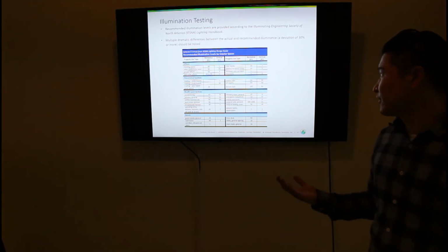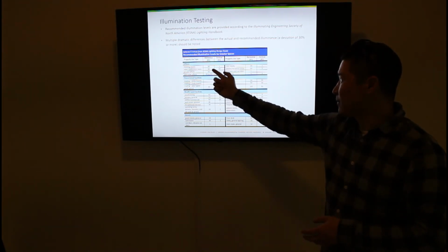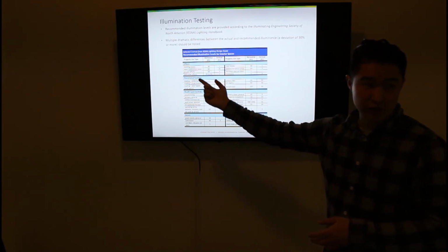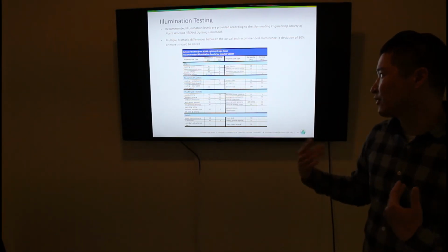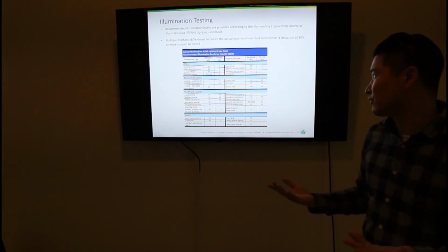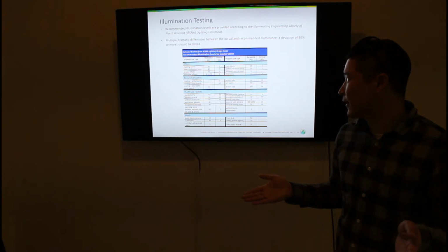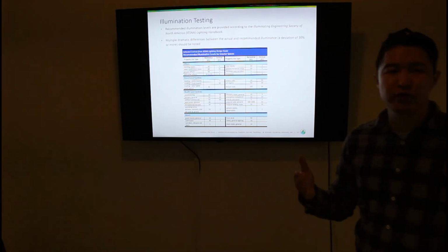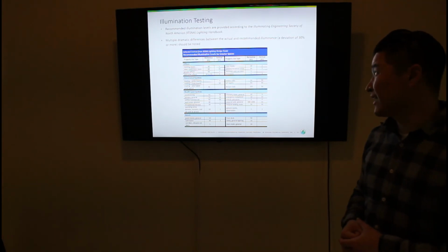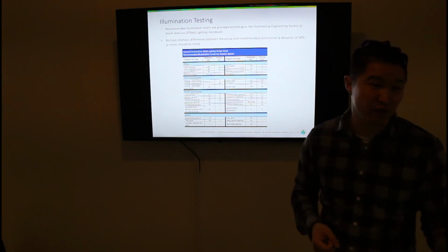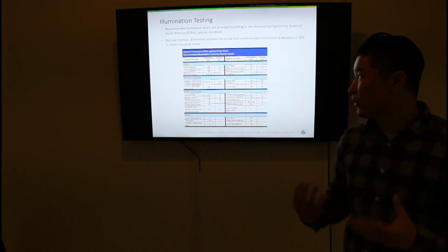For example, if you are looking at a meeting room, its recommended reading is 30 foot candles, then 30% of that, think of it as a third, so let's say 10 foot candles. What that means is we're looking at a range of 20 to 40 foot candles, okay? Anything between 20 to 40 foot candles, I will consider reasonable. What we don't want to see is something like 5 foot candles or 80 foot candles. If you see things like that, that's something you definitely want to note.